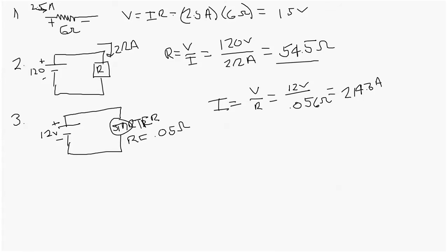reason when I go to buy a battery, I buy a battery that's got cold cranking amps of somewhere 500 to 600 cold cranking amps, because when it's cold outside and this motor doesn't want to start, it doesn't want to turn over to start with, and it's got a low resistance, it's got an unbelievable amount of current there that it wants to use.